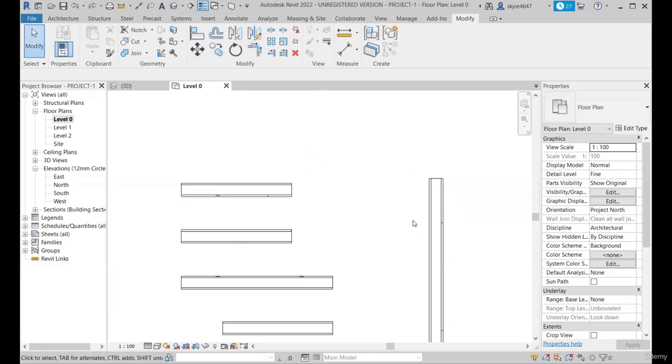So if I select the second element, you can see the corner is trimmed like this. I Control Z it again, and I will just extend this wall further beyond. Using trim extend can be a bit confusing, as it depends on which part of the element you select, above or to either side of the center line of the element that you choose first. If I choose this wall initially, and hover my mouse over the upper part of this wall, which is above the center line of that selected wall, you can see the dotted line is terminating wherever the selected wall's center line is. See, you can see it with the dotted preview that is available.